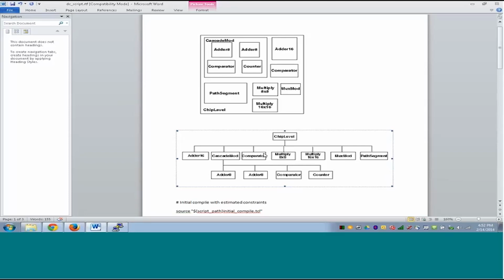There are many ways, you can do it through a Unix script or a Perl script. You can easily write out a black box Verilog module out of a netlist. You can even do it from RTL. The only information you need is the module definition and the inputs and outputs. That's it. No logic.